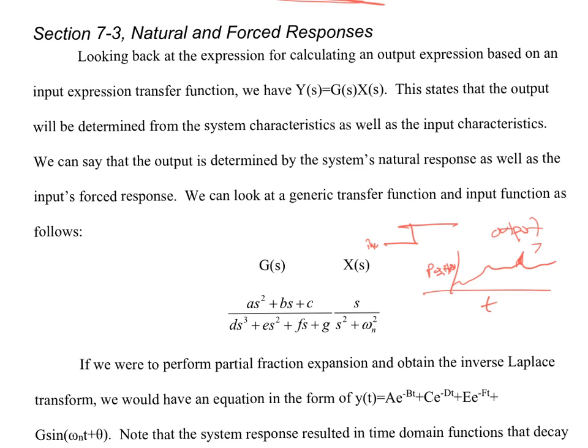So that was one of my proudest moments, because I had to work on Easter, and the operators in the control room, I think I told the story, warned me, don't go above 50% power. And how do you increase a nuclear reactor power? You just drop the temperature, which means you pull more steam out. If I kept cracking open the moisture separator valves, it could potentially have gone over 50%. The operators were yelling at me, you better not go over 50% power. And I'm looking at them saying, how do I know if it's going to go over 50%? I have no idea what it was. But anyway, it didn't go over that.